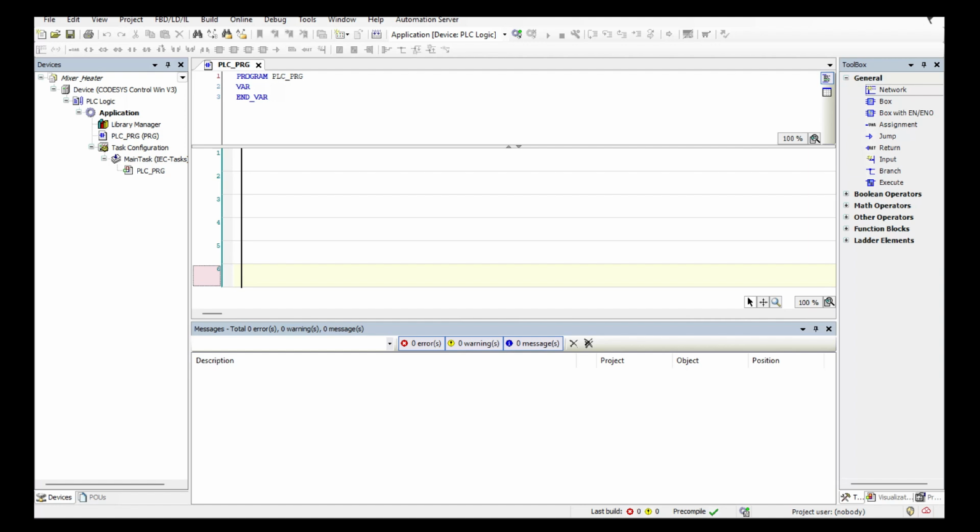So overall idea, what kind of programming this is. This PLC programming will be in LD ladder diagram, and in simple terms, this program starts and stops the system safely, checks when the tank is full, starts the mixer and stir, and the heater, uses timers to control how long things run, and stops everything automatically after a set amount of time or if something emergency happens. So let's start. There's six different networks we'll be using.